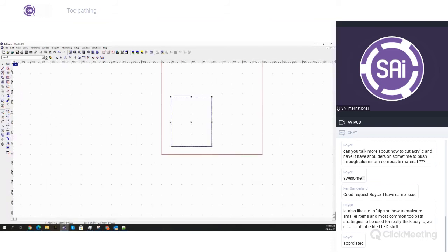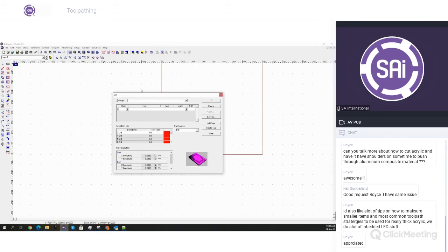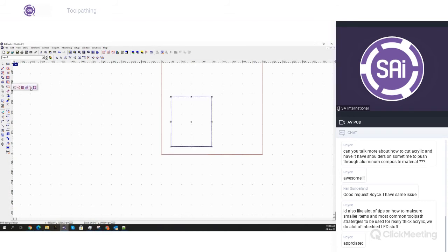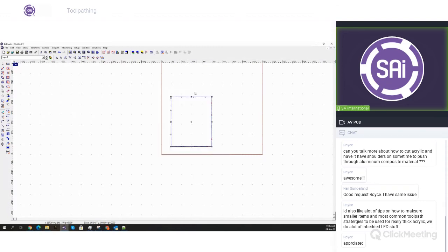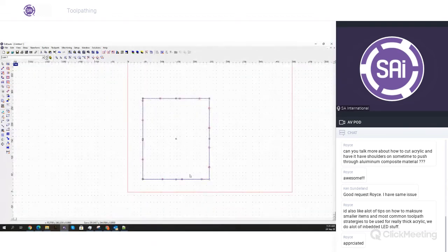Another possibility would be to use drill along a contour. So you also choose your drill. Here you have a spacing type: hold numbers, hold the spacing, just put it in the corners, inside or outside corners. Typically I would use hold numbers or spacing. And here, let's say you set, I want 15 drill holes at a depth of 4. And then based on your contour, it'll automatically choose the spacing for you.